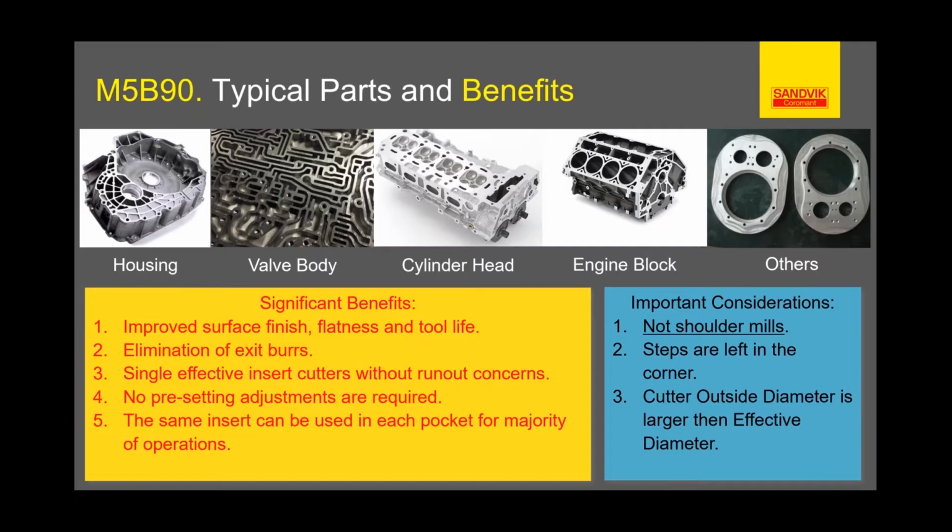The thing to remember is that these are not shoulder mills. These are face mills, much like you would think of a 45-degree face mill. They're not designed to mill into a corner. And the outer diameter of the tool is larger than the effective cutting diameter because of this step technology.